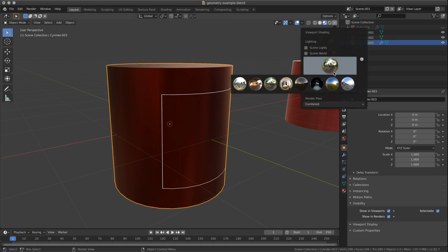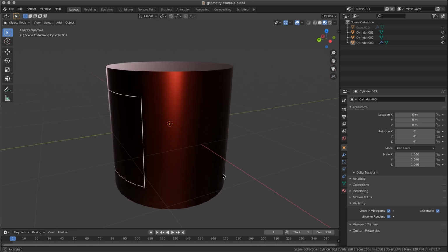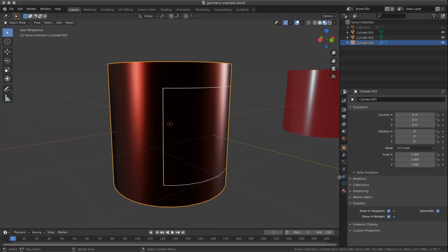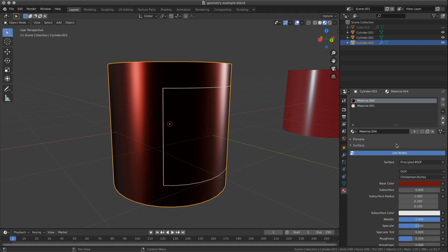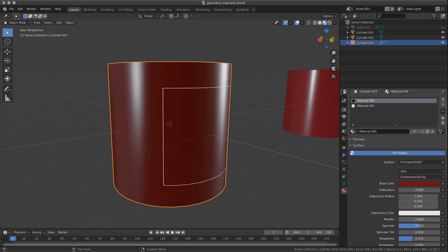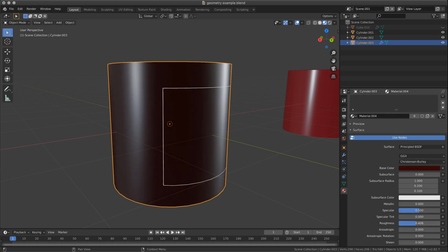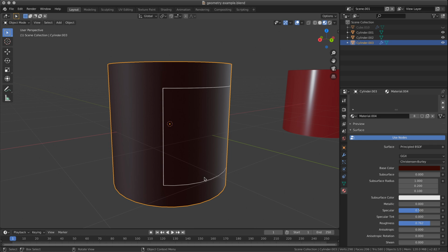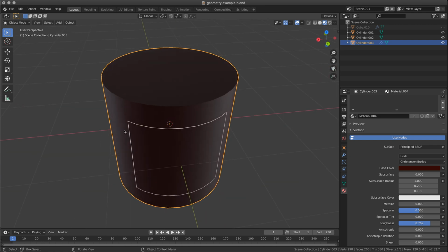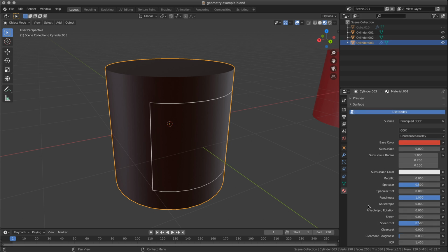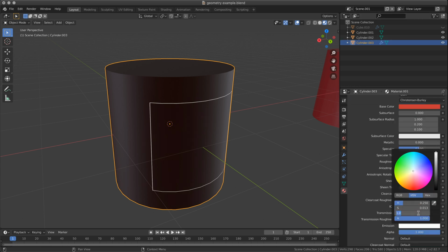Let's go with a darker environment. You can see that I have emission coming from there. Let's make it even more evident. So let's go with my metal and remove the metal for now and make it a very dark kind of material without any specular almost. You can see now I have a very dark surface with this emission here. Let's boost the emission material even more. Let's say we go from 1 to 2.